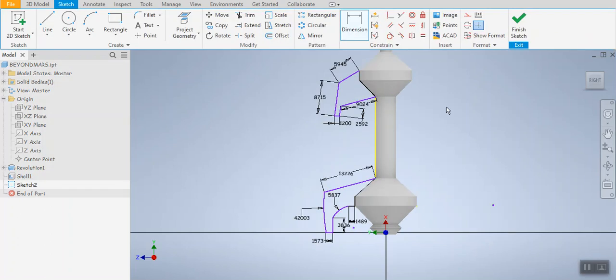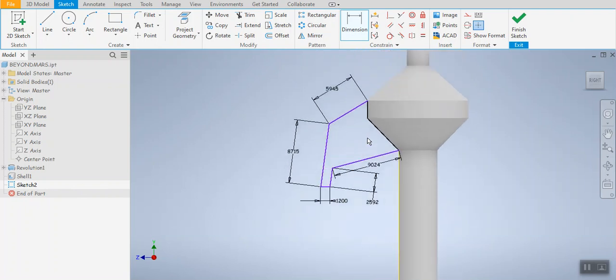Okay, so we're going to continue with the fins, and to create those fins, you need to select the plane first. So I'm clicking on this XY plane one more time and creating a new sketch, and this is sketch number 2. I'm in the sketch number 2 now. So the head fins attached to the capsule will be following the outside lines of the rocket, and you draw these two lines by just simply clicking on the line command and then selecting the points at the corners.